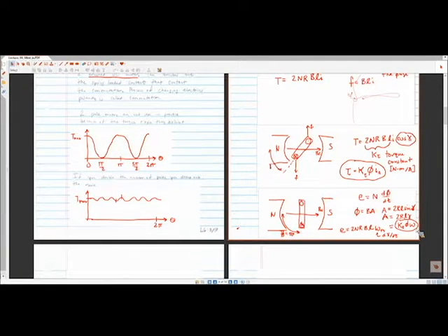But if it's a field-generated magnetic field, so that means a field circuit-generated magnetic field, that means we have some sort of coil creating that magnetic field. That is going to be dependent on the voltage across the terminals of the motor, and we're going to assume that that's going to be changing in time all the time, especially when we get to dynamic analysis.